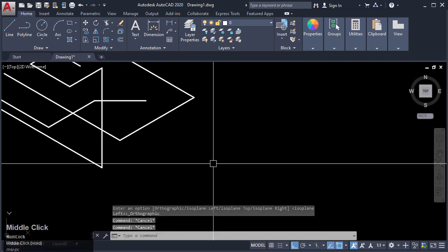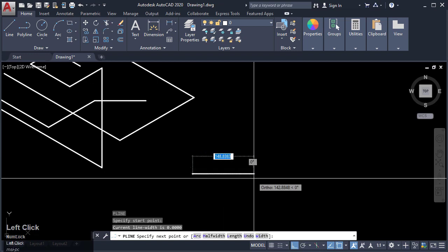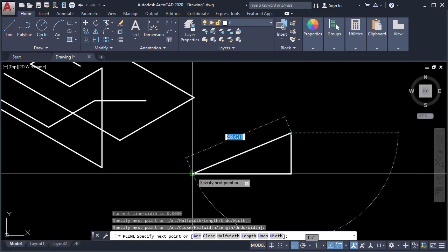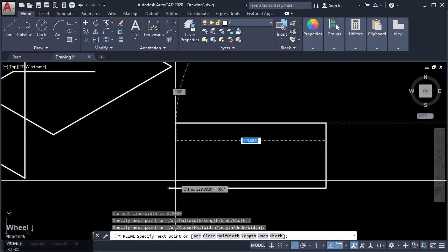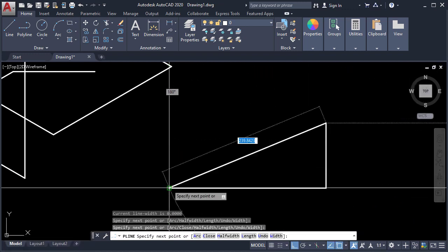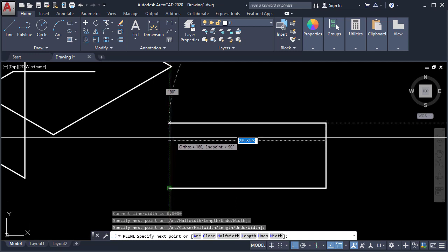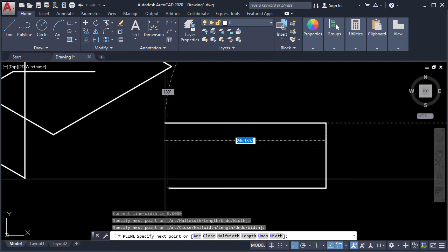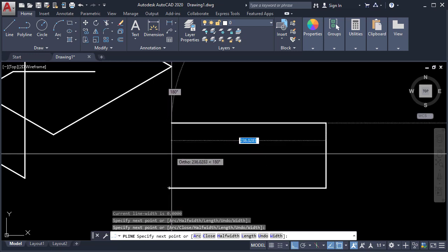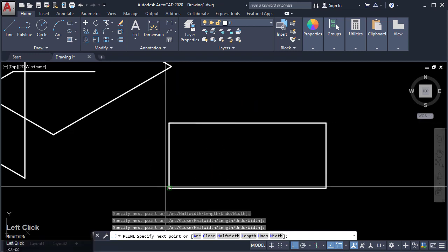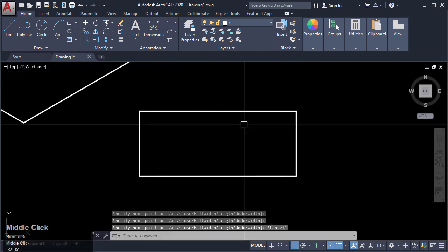Let's demonstrate how that works. So let's say I have in here a line, and I wish now to extend that line without typing the distance, and I want that line to reach towards this location. So what I do is I bring my cursor close to that location, and one thing that you will notice is that a green dashed line is going to appear, indicating that if I click that line, it will terminate in alignment to that point. Okay, so activate, going close to that line, then click, then automatically it will close your object.